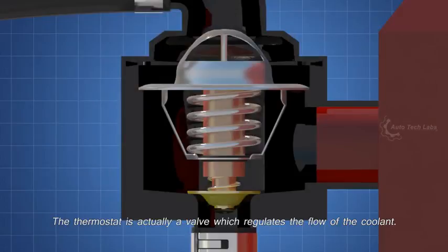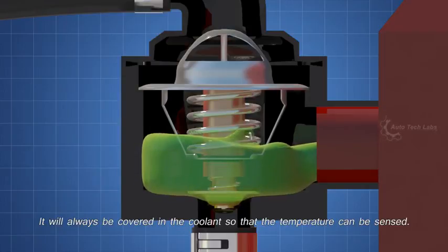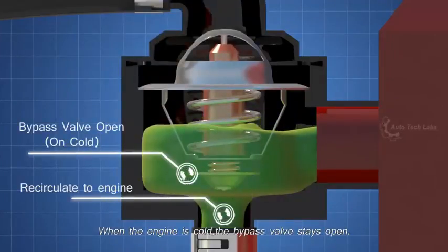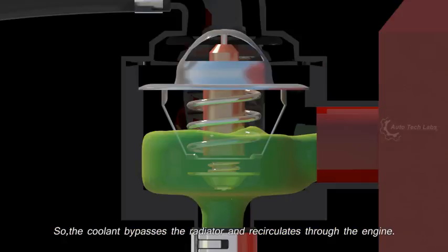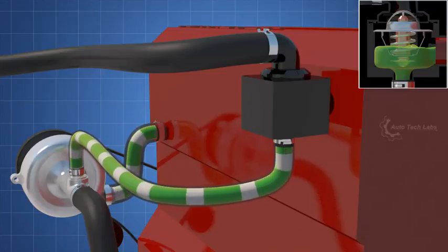The thermostat is actually a valve which regulates the flow of the coolant. It will always be covered in the coolant, so that the temperature can be sensed. Let's start the operation from a cold engine. When the engine is cold, the bypass valve stays open. So, the coolant bypasses the radiator and recirculates through the engine. This helps the engine to heat up to operating temperature quickly.